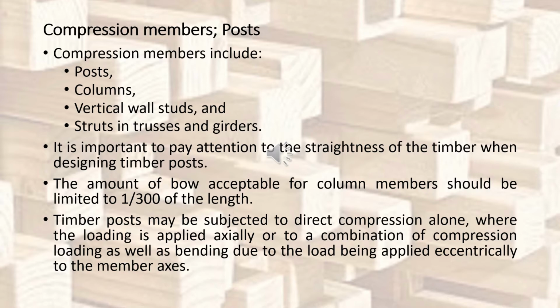Right? So the amount of bow acceptable for column members should be within a specific limit, normally 1/300 of the length. Right? So the bow limit should be 1/300 of the length.